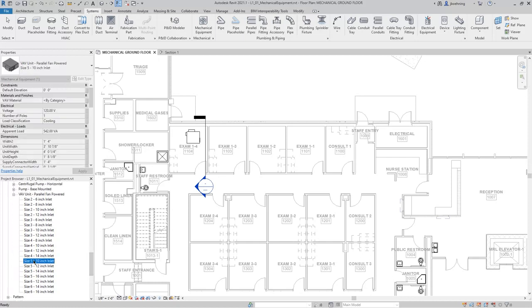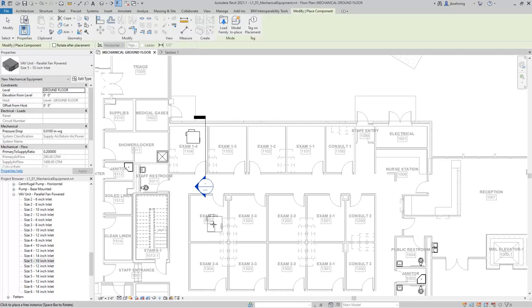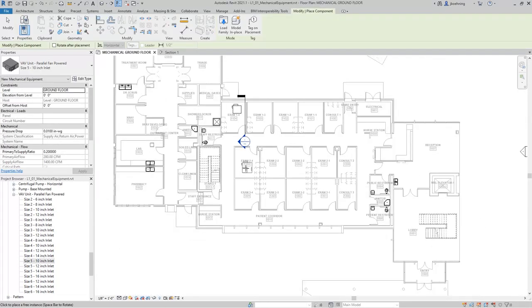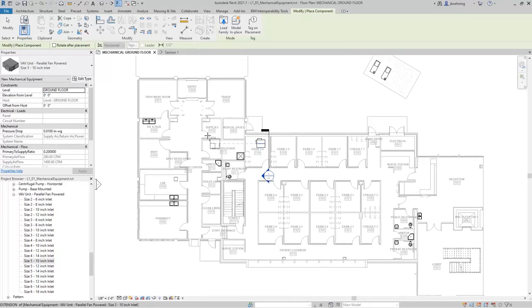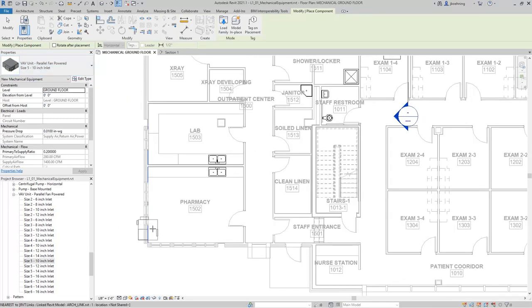And if you select a type and drag and drop it into the drawing area, the mechanical equipment tool activates and the type that you selected to drag and drop is selected in the type selector. Now you can once again do the same thing and place it as needed. In this case, I will set the elevation before placement and we'll click to place it, and I'll click Modify.